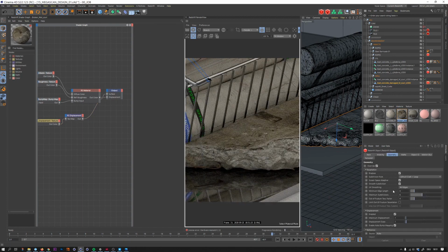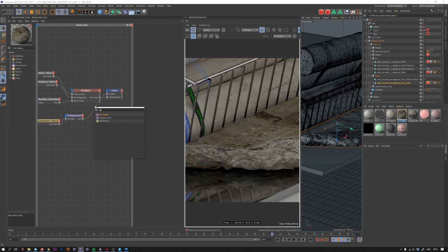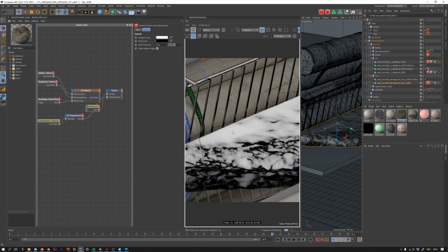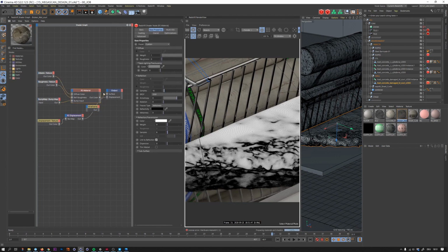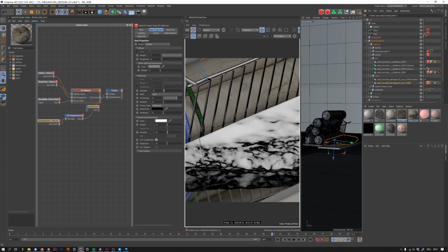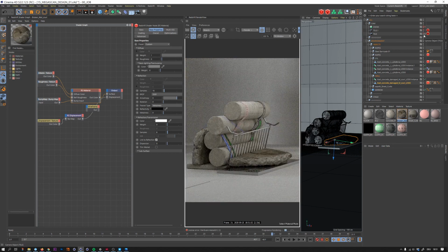So displacement, well, mostly I'm not using screen space adaptivity here, and let's try to see what's happening with 3 subdivisions. So wireframe, press C for previewing, and I think 3 is a reasonable value. So it's not that highly tessellated. We could actually go 4 if you're closer, but we are not that close. So 3 is definitely enough for that.